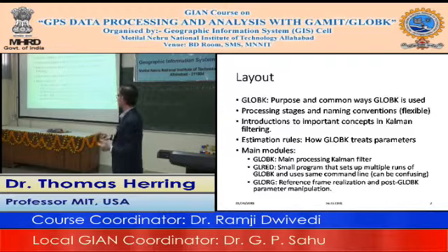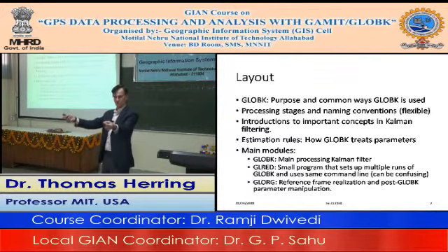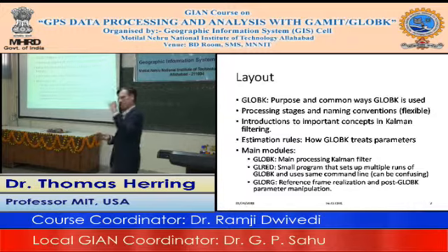Then we'll look at the main modules, which is GLOBK itself, which is the main processing Kalman filter. GeoRed, I think we mentioned that in the other lecture, is a small program that actually just sets up multiple runs of GLOBK. But it uses exactly the same command line. So people get a little confused about that. What it's doing is simply taking that command line and feeding it to GLOBK. Instead of just processing one thing, it does a whole series of days at the same time.